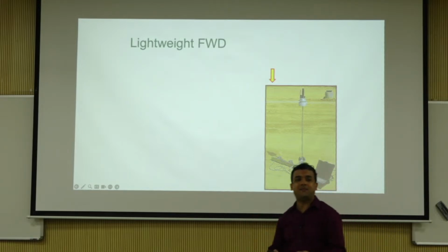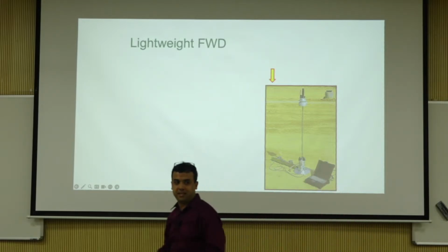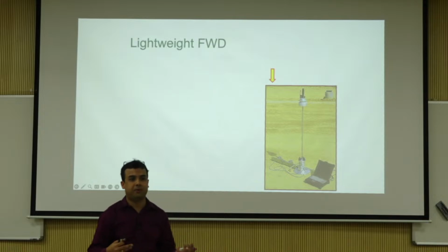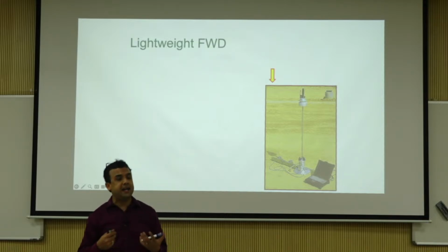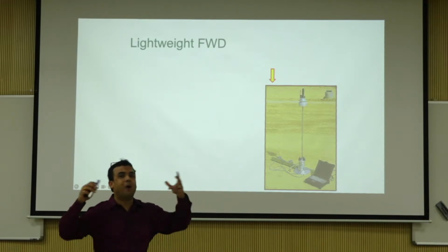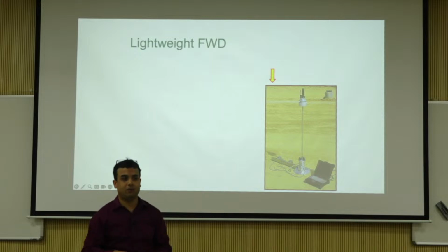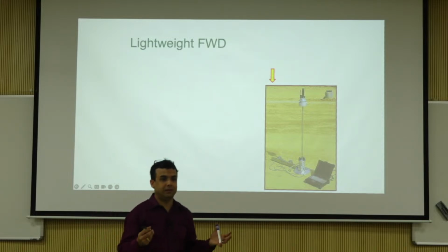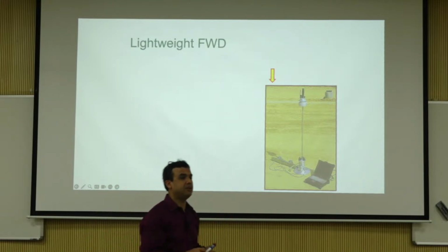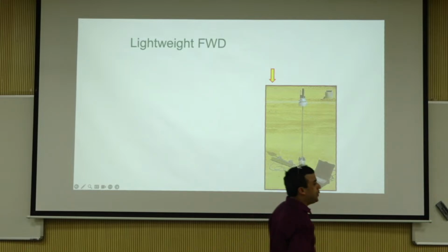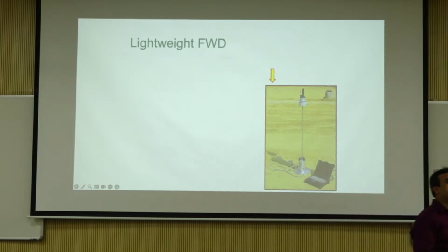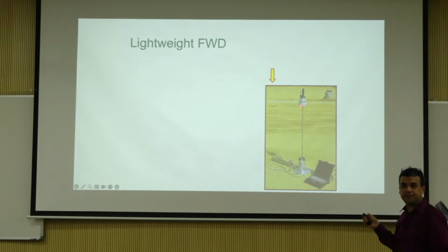Now if you have a subgrade construction happening, you're not going to get a vehicle on top of that. It's not possible, and it's not very portable. You probably have one in the state of Odisha or maybe more. I don't know. That's a common challenge, right? What a lightweight deflectometer does, it's a portable device. You can carry it by yourself. You do the exact same thing.